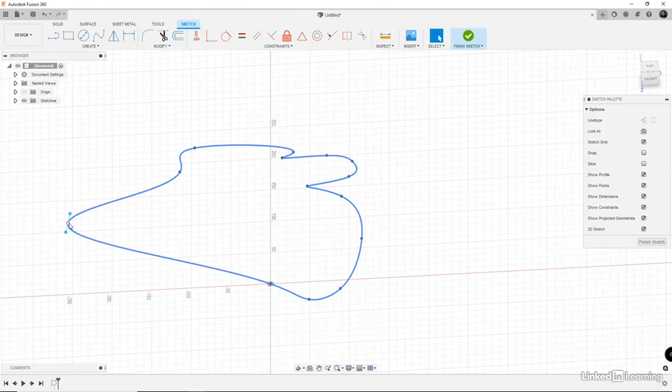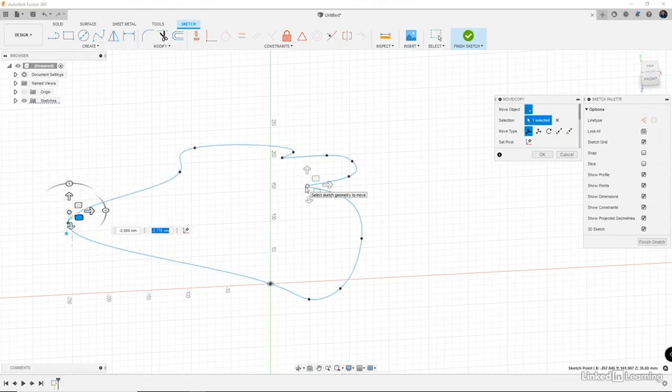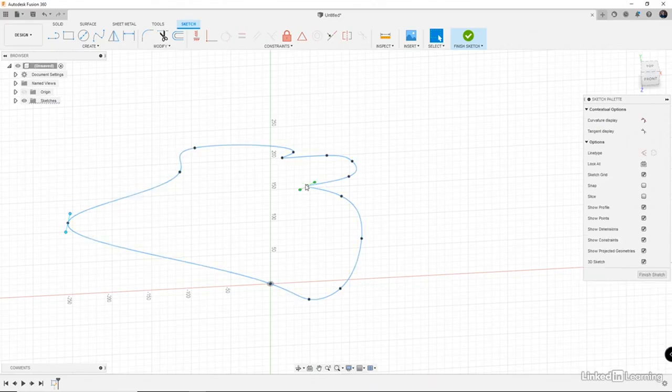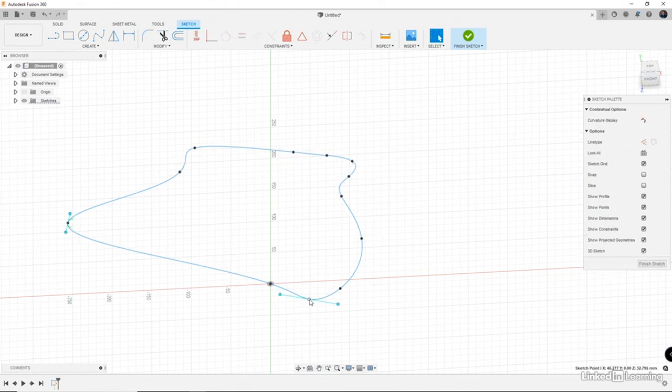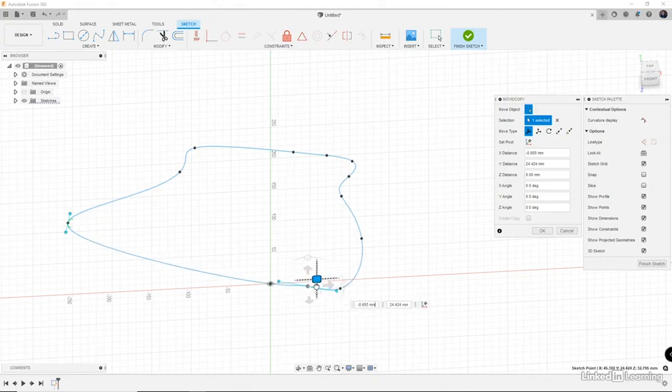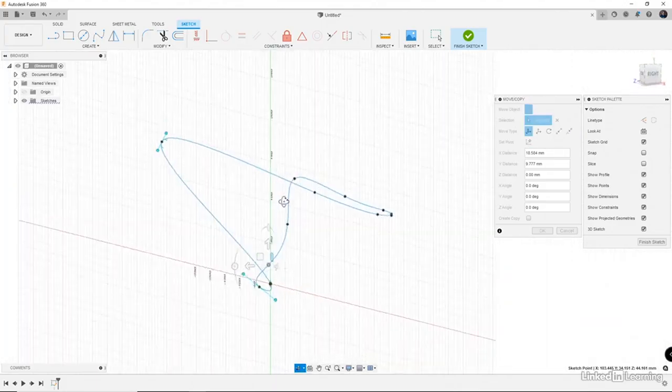And what I mean by drivable is that I can edit these however I want, meaning I can move any of these points. I can drive the spline however I see fit. Or if I come in here and I say, you know what, I don't like this point, I could actually delete these points like I would in a normal spline. So I can make a new geometry. So we can move any of our set points, and you can see how this simple move is driving so much of the geometry down the road. So this is an incredibly powerful setup so that you can drive some really complex geometry.